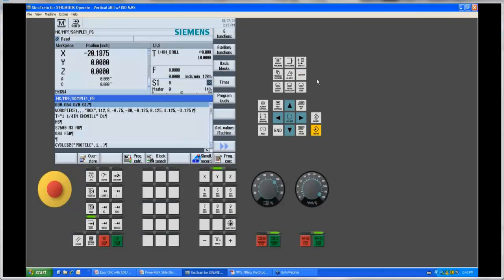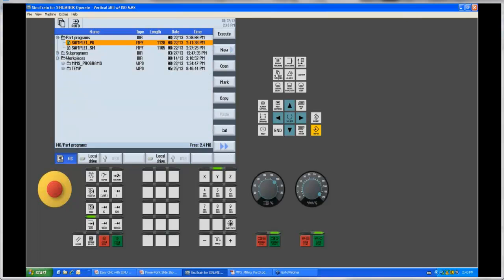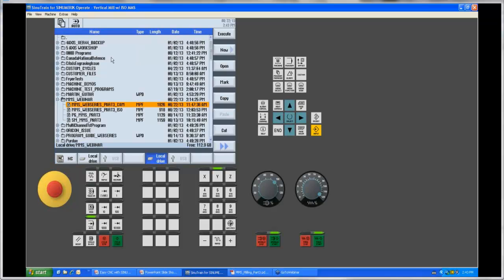Good. So with that being said, I'm going to go back to Program Manager. We are now going to go get this program. It exists somewhere. So we're going to say that my local drive, which happens to be my docs on my PC, we're going to treat that as if it was the network. So your programming department created this file, you posted it on some folder somewhere. So the operator or you would physically just select the network drive function, folder, if you wanted multiple folders, or just in a base root folder.